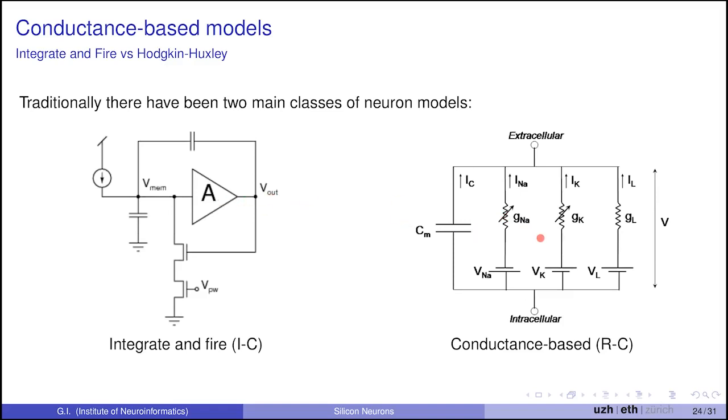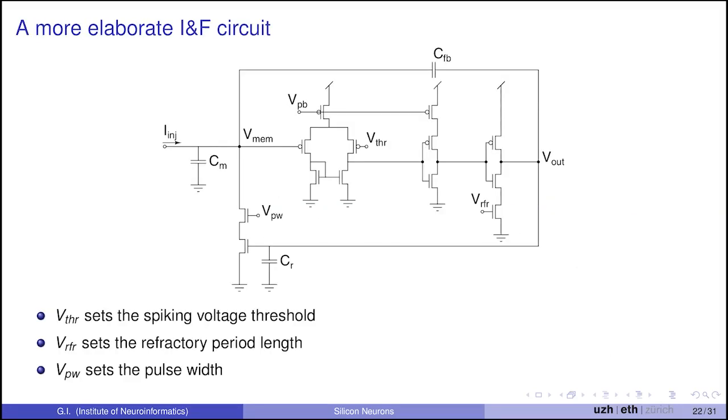But fortunately, also from theoreticians, sorry, there was a question on VBP on the previous circuit. It's connected to the first and to the second. So this bias voltage here is a subthreshold bias that's making this current very small, and it's making this current also very small.